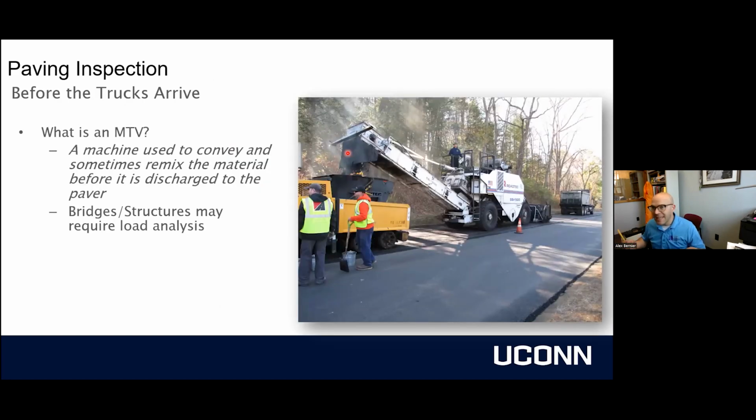So the next thing we're going to do is check our equipment. And one of the questions we want to ask is, can we use and are we using a material transfer vehicle? That's what this is here. I liken it to a giant brontosaurus. You've probably seen these on a construction site. They are massive. And the reason is, like this particular model, the Road Tech, it can hold an entire truck or more, up to 35 tons of material inside it.